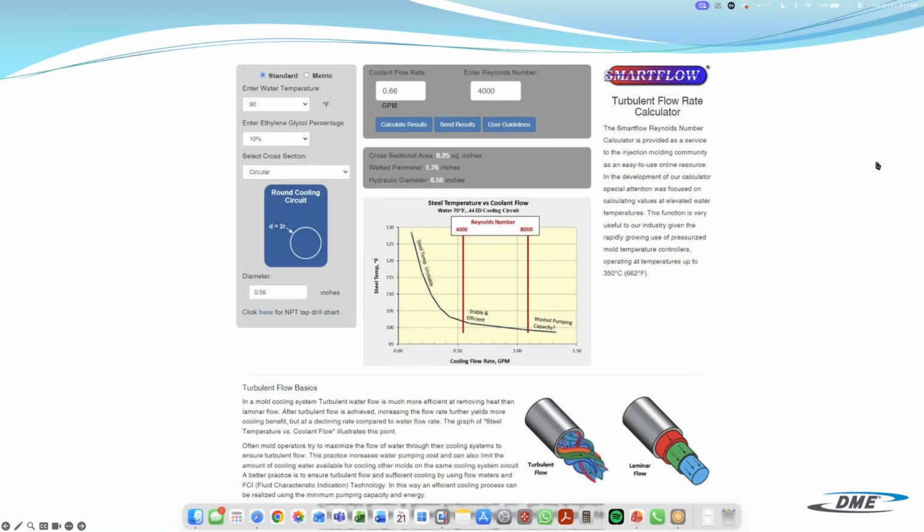Okay, great. And then the second question is, how does pressure affect the flow rates? So pressure is going to push more flow through a given diameter. If you need more flow through a circuit because you've got blockage or you've just got a tumultuous path, you're obviously going to have to increase your pressure to get more flow through there from a pumping standpoint.